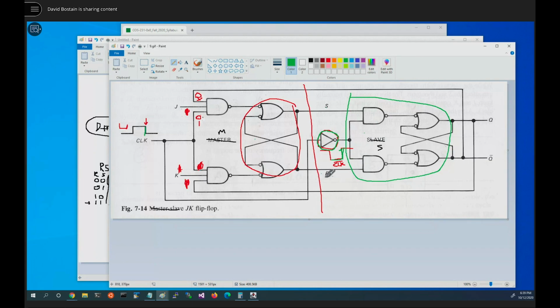When clock drops, it's the rising edge of the not clock, so it's basically a low-going edge that's created by virtue of these two clock signals, and it only works because there's a small delay. By the time the signals are stable here to be gotten, this clock will rise and snatch it in and become the thing that gets transferred over to the latch on this side. So that's a fairly crafty way of getting that to work. Nowhere in there did we need a capacitor. We didn't need to do it.